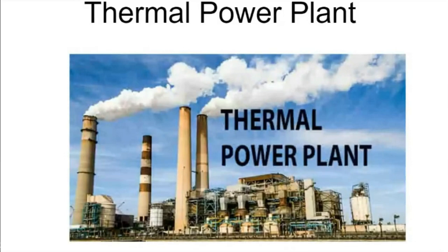Okay. So if we talk about the thermal power plant, we can install it where we can get the most prominent fuel, that is our coal. If you are getting coal in a very abundant quantity, then this place is very useful for our thermal power plant. So that is the very first point. Second point, as you say, it works on converting water into steam. So we require a large amount of water. Maybe it is required for cooling, or maybe for converting it into steam. So we require a large amount of water.